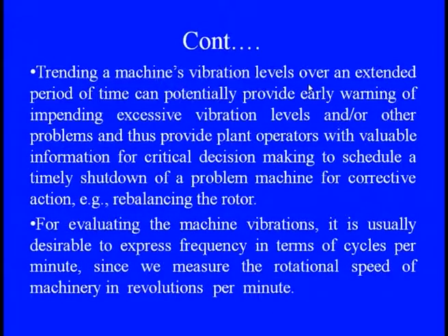So for evaluating machine vibration, first we need to see what exactly the desired level of the frequencies are, and then what exactly our amplitude is, which we can effectively control at that point, or whatever amplitude is being generated, we can say this is the usual form of the amplitude at the particular frequencies. If we can measure these, we can say the rotational speed of the machinery with this RPM, and we can calculate the dedicated frequencies which can come when any rotational features are there: the rotor, bearing, gear, shaft, whatever.